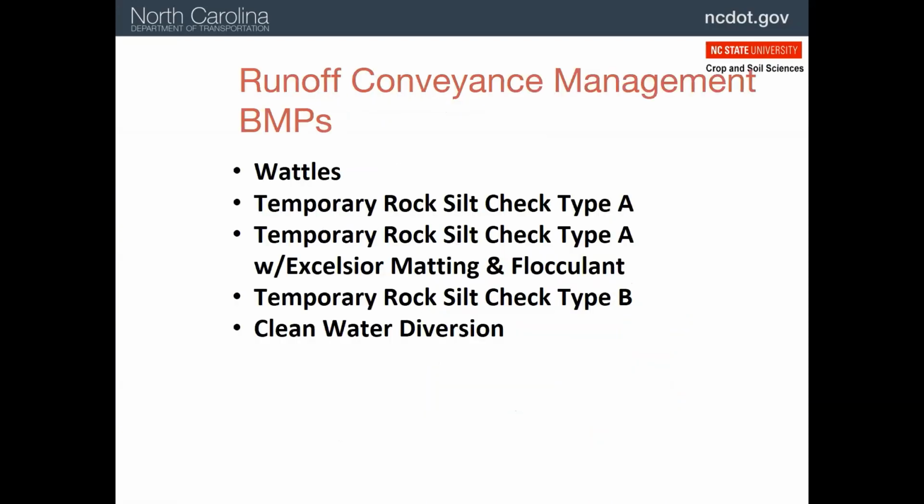Well, we've reviewed different ways to use ditches to direct water where we need it to go. We also have ways to prevent the ditch itself from eroding and adding sediment to the already heavy load in the runoff. These are called check dams, and the check means the flow is checked or slowed to keep it from picking up too much velocity and sediment. Here's a review of each of these.